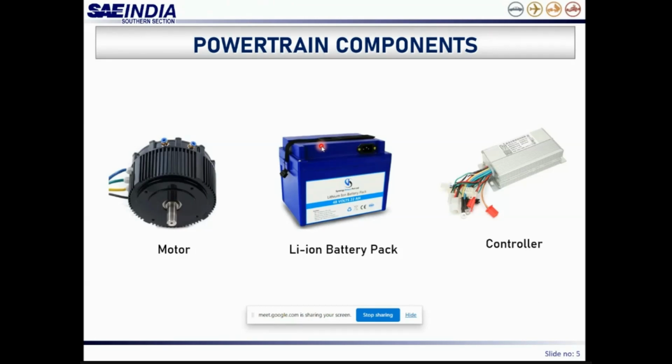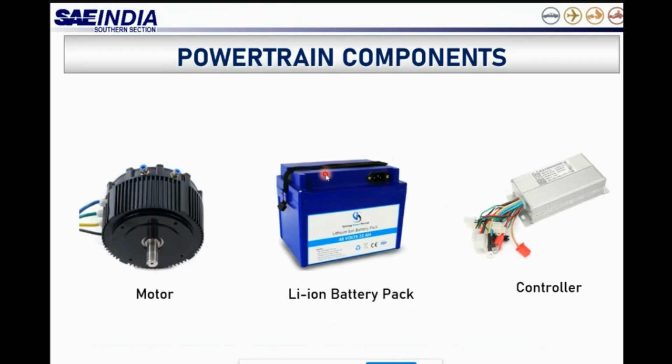If I ask you, what is one key advantage of increasing the voltage? Your power is voltage times current. So when the voltage increases, the current passing through the wires can be smaller, which has a direct impact on the wires that you are going to use.